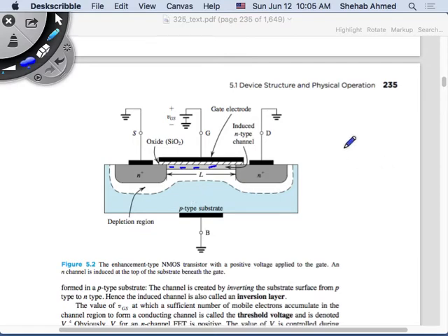And everybody is okay with this idea of overvoltage, right? It's the voltage on the gate, between the gate and source, beyond the threshold voltage. So the overvoltage is VGS minus VT. VT is the threshold voltage required to start creating a channel. If I want to create the channel, I have to have the gate to source voltage, VGS, be at least the threshold voltage.